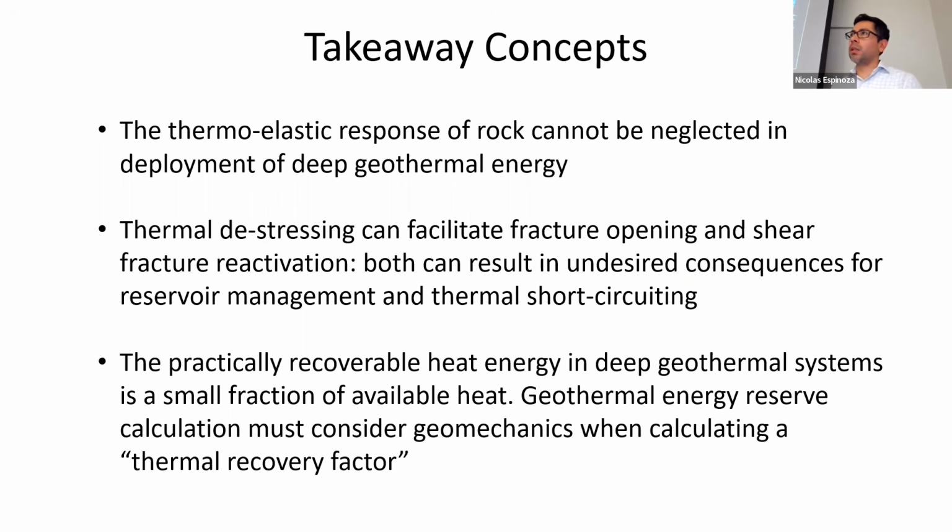Remember about thermal destressing. That happens when you lower the temperature and you have more rock around you. So the rock is not free to shrink, but instead you have a decrease in the stress, which in some cases can create or reactivate fractures, and can lead to thermal short circuiting, both of which we do not want. And those are also going to affect the performance of a geothermal system in terms of power capacity. So I think this is the end.